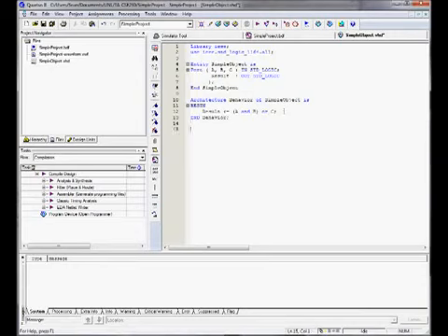So now we're just going to save it once more, and we're going to compile it. In order to compile it, there's a couple of different methods. There's a button on the drop down on the side here. Should be this guy, analyze, or you can try to compile it from up here again. In order to do that, there's a little trick in Quartus that you have to notice, and we'll come over here to simple object, and you left click on it, and then you right click, set as top level entity.